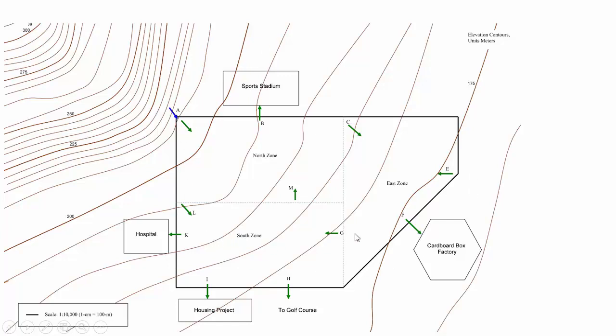relatively less steep. But in that design project, what you're going to be doing is based on estimations of how much water people would be using in different parts of the city, and so how much water is going to be coming out of the network at these green arrows. You're going to figure out how big the pipes should be between the junctions. And so you'll use either WaterGEMS or some other design tool in order to size the pipes and to optimize and iterate and make it better and more efficient until it's the minimum cost that still satisfies the objectives.